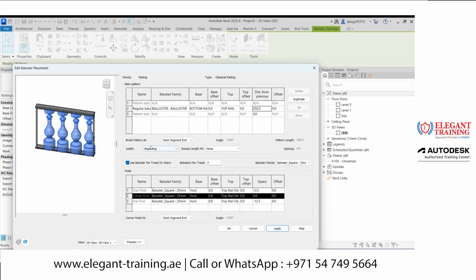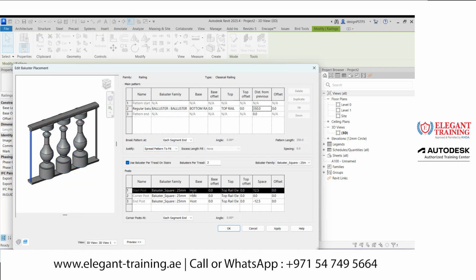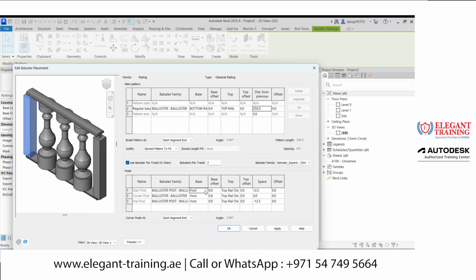But the justification starts from the beginning. So what I can do here, I will turn on the spread pattern to fit. Now let's choose a start post. For the start post, I will change this to the baluster post. Okay, and for the end post also I will use the same thing. If you click apply, you can see that one is loaded over here. The host for base will be the bottom rail in all cases, and the host for the top rail will be the top.